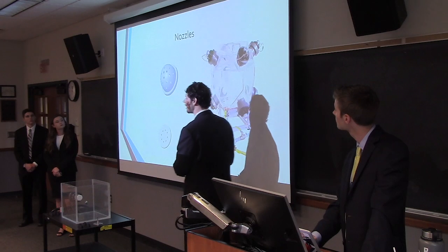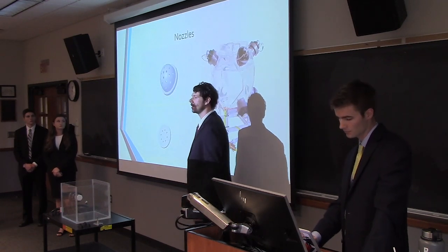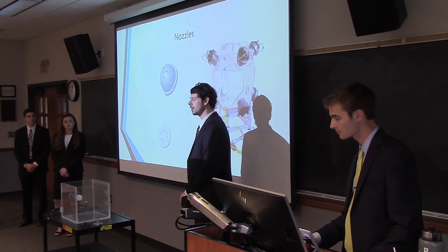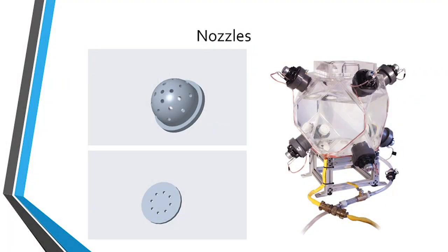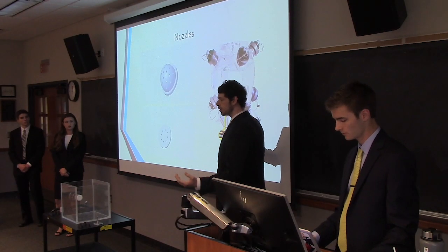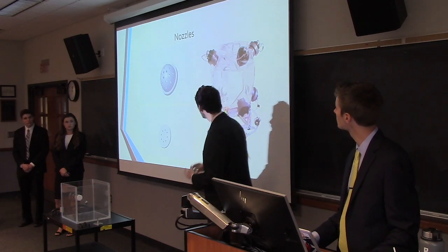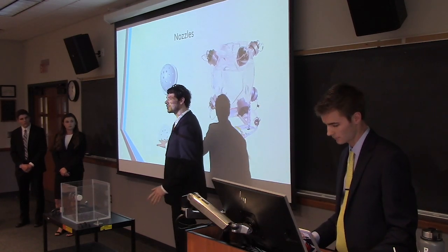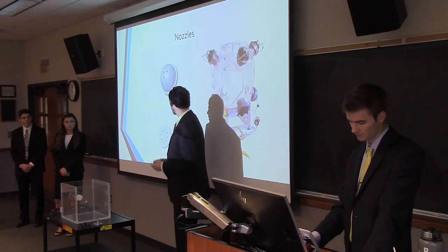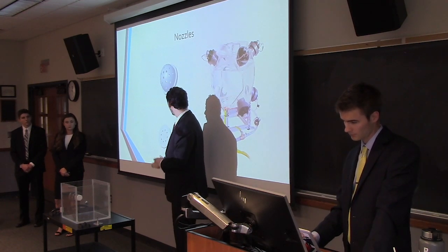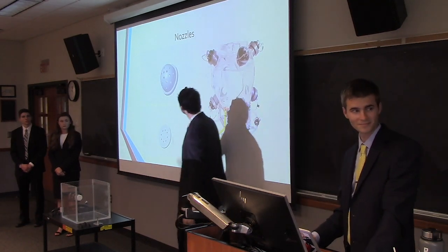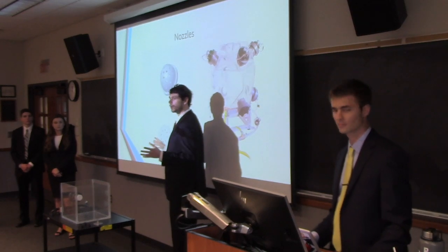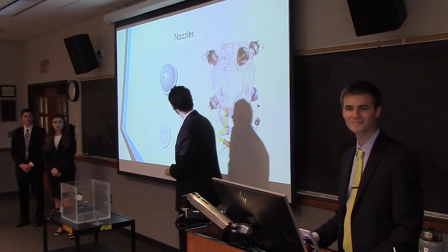Once we took that data, it soon became very apparent that the turbulence levels we were getting were just too high. If you look at the tank, all 8 actuators are pointed at the center, and that means all the water jets were focused in one small area. The original jet was just straight holes. There was no dispersion other than small fluid jet dispersion. But mostly the water jets were focused to the center of the tank. Our solution was to make a dome nozzle to spread out the water being displaced by the bellows.